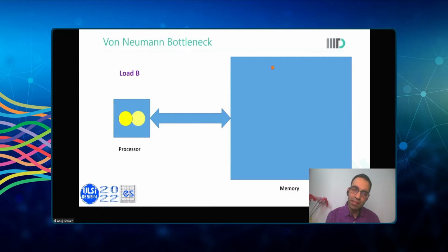SRAM sends the second set of data to the processor. The processor does the addition, a new data is generated, and then you launch another instruction, which sends another set of data to the memory for the writing operation. So for just one instruction, we needed to interact with the memory 6 times.